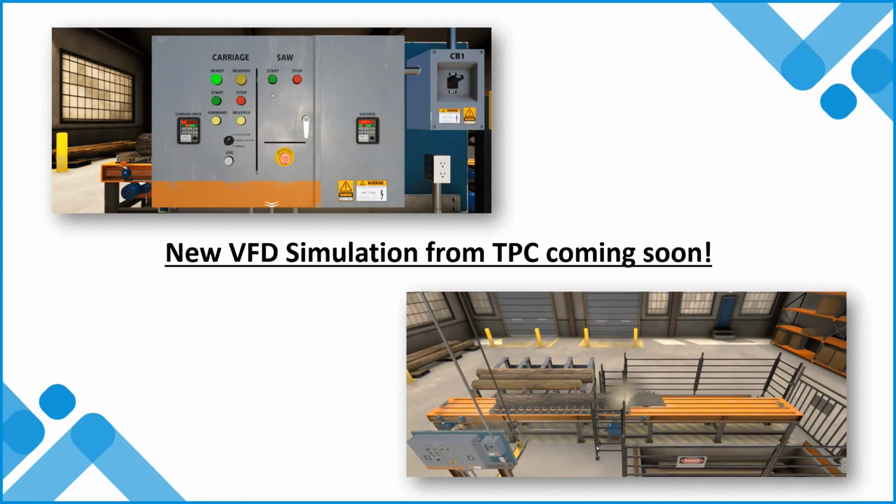Good call. What are your thoughts on shielded control cables, and would you recommend using them for VFDs? Most definitely. Any of the controls have to be shielded. They have to be at least 3 foot away from 480 volt power wires, the conduit does. You've got to be careful. If those aren't shielded, you're going to have a real problem controlling that drive. Excellent.